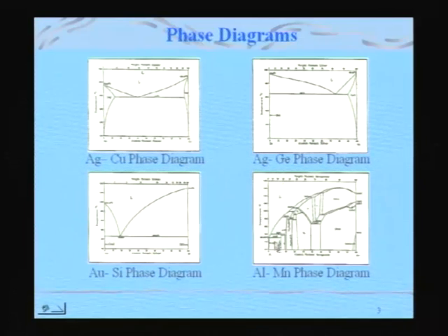And so this was the aluminum manganese phase diagram, where at 14% manganese you have a phase called Al6Mn. That is the phase which is called rational approximant for quasicrystal. What is the meaning of rational approximant? That means its crystal structure is very close to that of a quasicrystalline arrangement of atoms. So there are certain crystal structures which are available in various phase diagrams whose structure is to some extent correlated to the quasicrystalline structure, and in all those systems it is very easy to get quasicrystals.